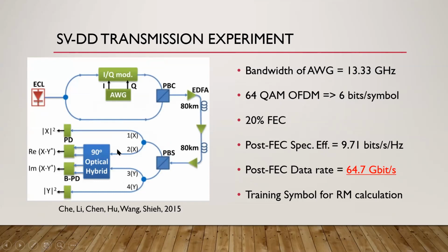But basically the circuit involves an external cavity laser. The signal from that goes through a coupler, so that's split. On the bottom rung here, we've got the pure carrier. And then on the top, we've got the carrier, and that then gets modulated with the information signal. The two of them then come into the polarization beam combiner, so they're both combined into the one signal on orthogonal polarizations, transmitted down the fiber cable over 160 kilometers.